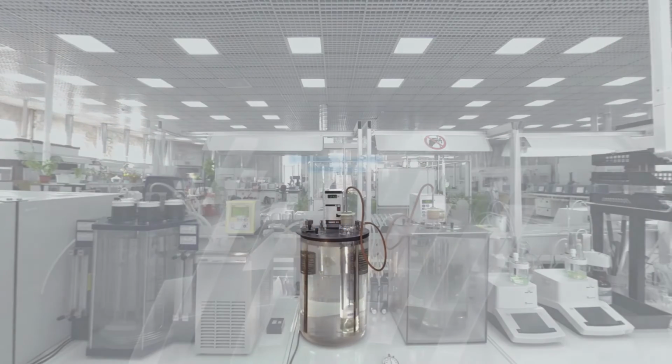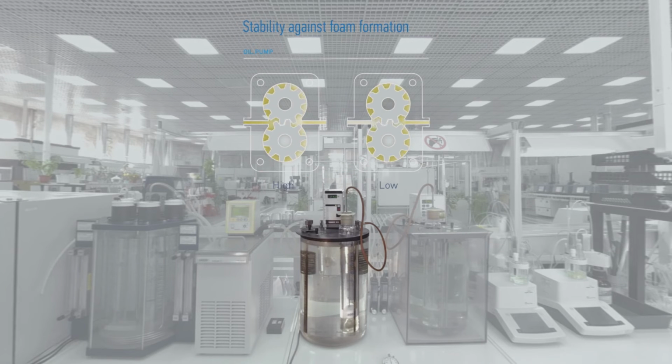The ability of the oil in preventing foam formation at high rotation speeds directly affects the continuity of the oil film in a friction joint. If the foam is trapped by the friction unit instead of pure oil, this can result in accelerated wearing of parts, overheating, and oil oxidation.